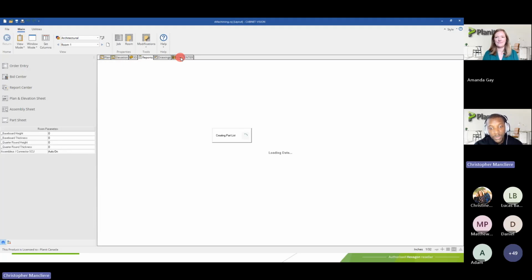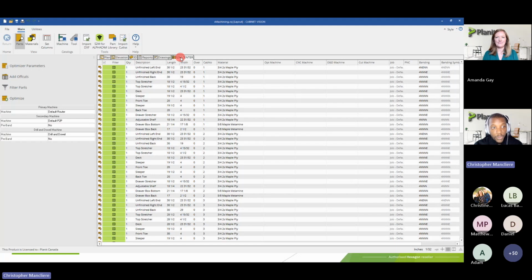TM center, you will always be importing parts. So the part list is where TM is importing the part with the materials and the operation associated with the parts. So to access the machine catalog, that will be at the very top in the catalog toolbar, and you have the machine button. So that's where you can change properties on each machine you might use for your optimization.